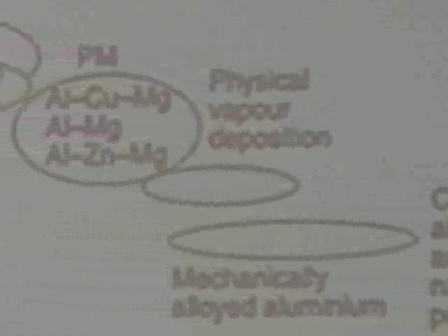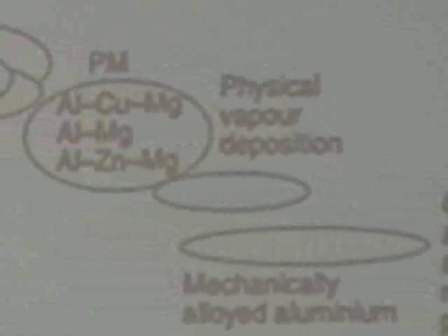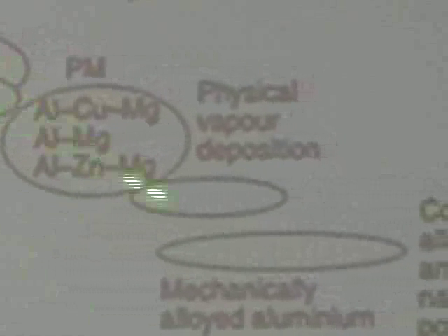Well, if you want to get creep and make things super plastic, you want fine grain, and this shows the fine grain size as a function of strain rate for aluminum alloys. This is powder metallurgy aluminum alloys. Now you're getting into superplastic forming strain rates of a tenth per second, which means that you're going to get 100% strain in 100 seconds. So in a couple of minutes, you're actually going to pull this thing. It's almost like my taking the clay and pulling it before your very eyes.